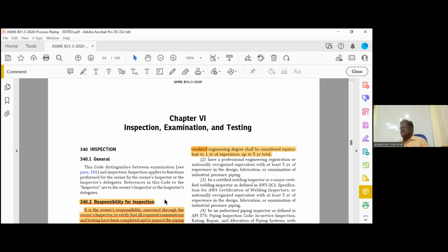Girth means circumferential weld. First, these are the girth weld requirements. Category D, 100% visual, no radiograph. Girth weld, what is the NDT requirement for category D? 100% visual, no radiograph. Category M and normal fluid, 5% visual, 5% radiograph. Severe cyclic, 100% visual, 100% radiograph.